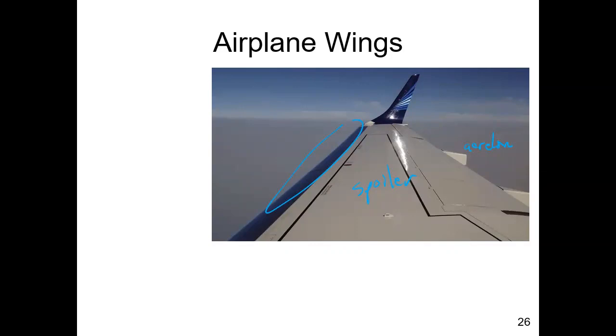However, there are also designs to maintain a laminar boundary layer almost over the entire leading surface. As long as you do not have separation, you're minimizing the drag force because it's a form drag. There are ways of keeping the boundary layer on the surface by having vents or other structural measures to even preserve the boundary layer. So you can either trip the boundary layer or you can try to keep it on the surface.